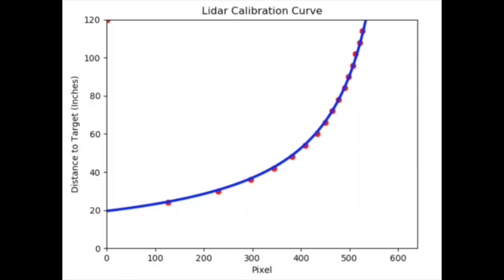Similar to the LiDAR prototype with the laser pointer, I set the sensor at known distances away from a wall to allow the camera to record information about the red pixels. Instead of reading manually how far away the laser pointer was from the center of the camera frame, I utilized a Python code developed by Professor and Dr. Mitchell that averaged the red line laser points together to find the center pixel distance. With these known sensor distances, red pixel distances, and a theoretical curve, we could calibrate our very own LiDAR sensor.